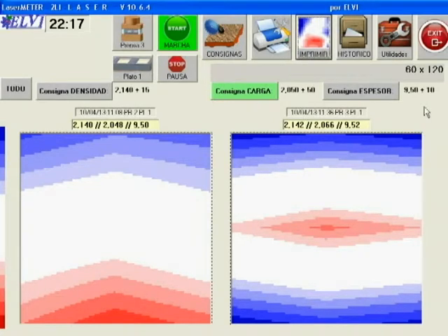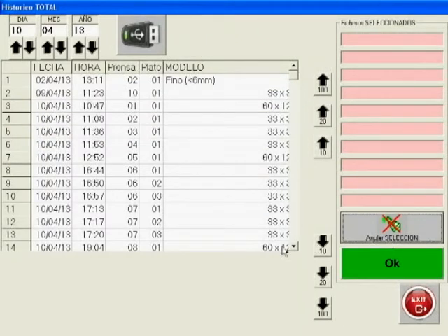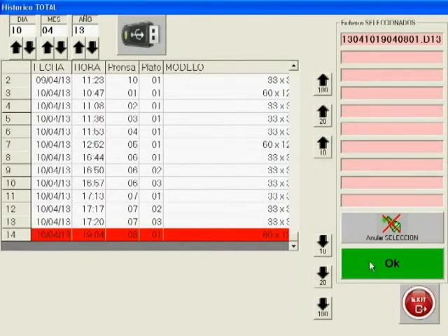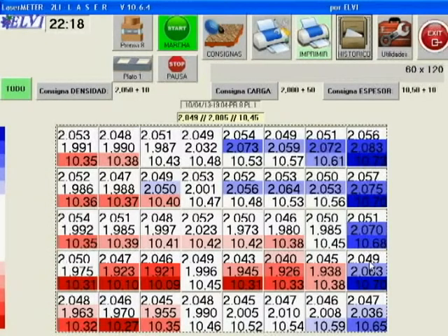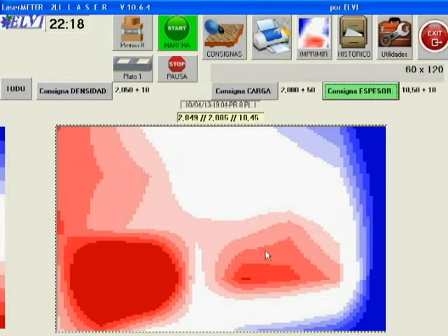When we speak of porcelain tiles, usually large and which also have to be polished, the importance of uniformity in thickness is of maximum importance, since it determines spending on polishing machines, and since the variation in the thickness directly depends on the distribution of load of clay, it is essential to have this parameter, which cannot be obtained by traditional methods of control. In this example we see a 60 by 120 tile, in which we appreciate variation of thickness in some areas.